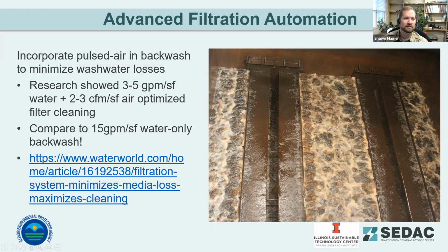And we do have another poll here, so we'll launch that. Which is the most effective backwash control option? Manually timed backwash operation. Differential pressure triggers the backwash, but it's a timed cycle. Differential pressure triggers the backwash, and then the duration is controlled by a sensor. Or you're manually triggering that backwash, and the duration is controlled by a sensor.